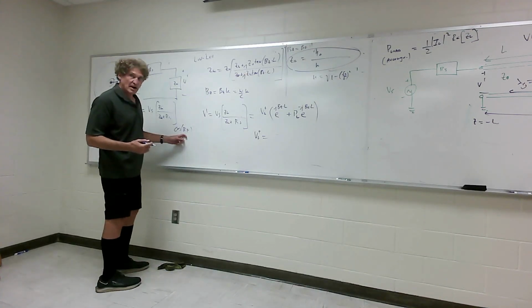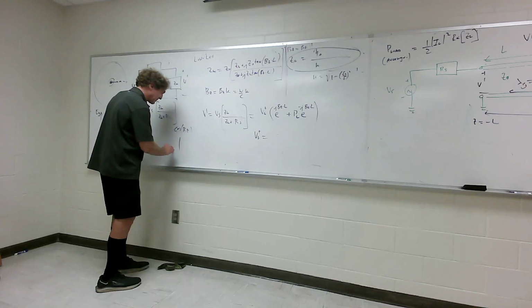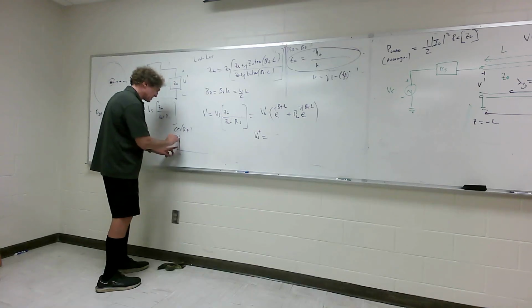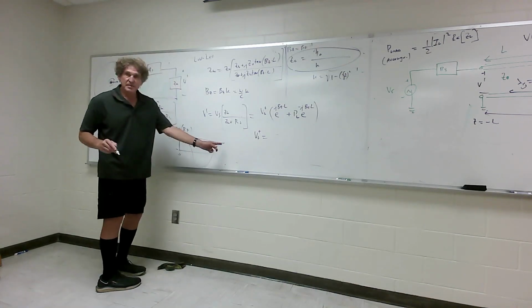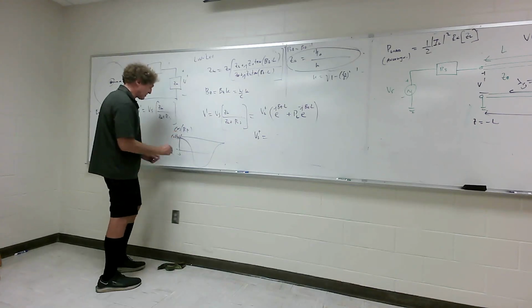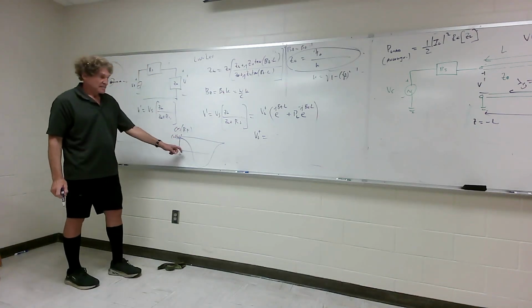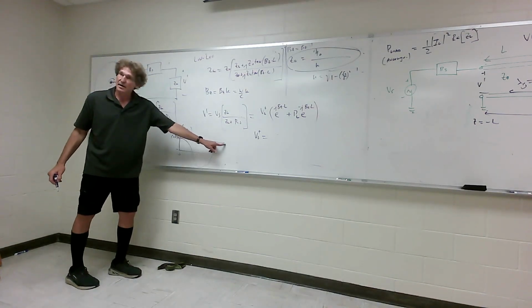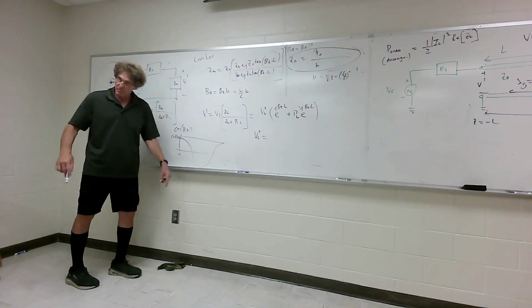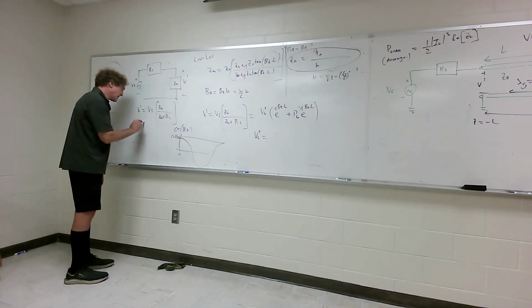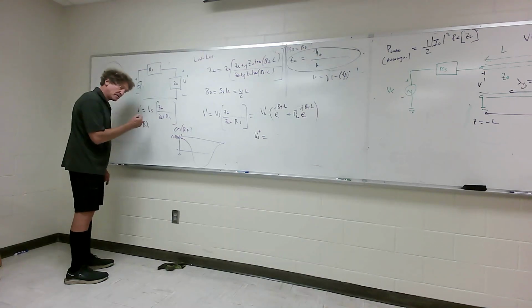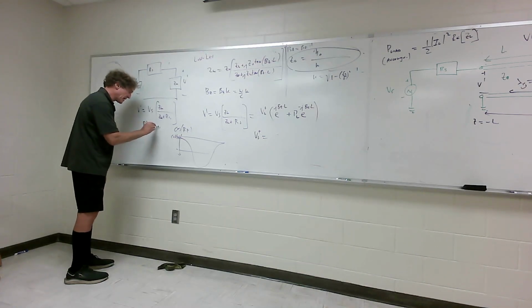If you think about wavelength and you were plotting just the cosine variation here, cosine of beta times z, that's 0. But you'd see it starts here, goes down, comes up, and where it begins to repeat itself is a wavelength. How do you get that? Well, that's 0, right? This has to be 2 pi. It has to be 360 degrees. So you can say beta times the wavelength, this would be in free space, is 2 pi.